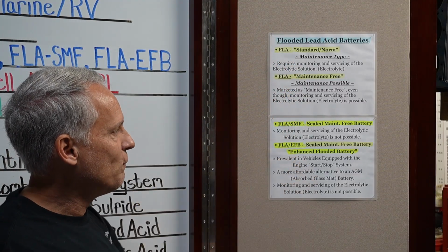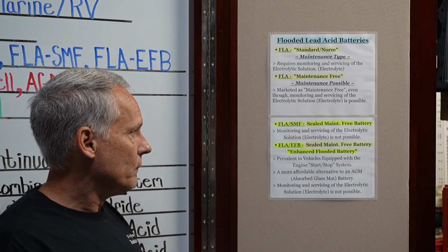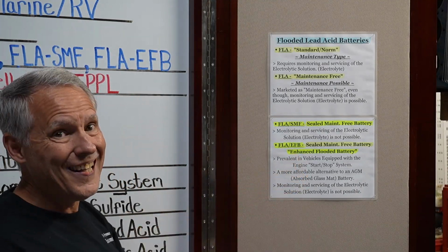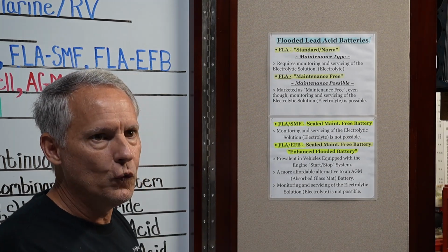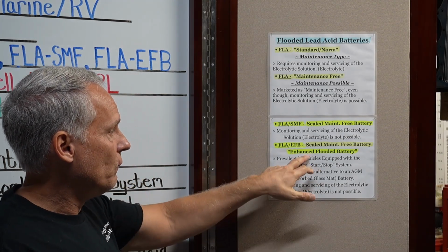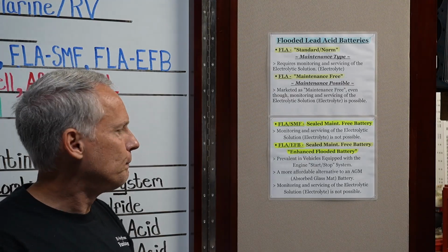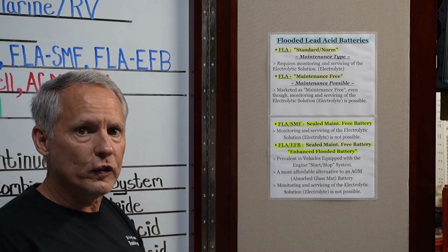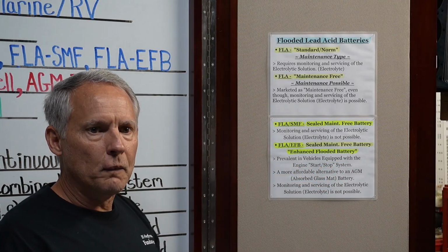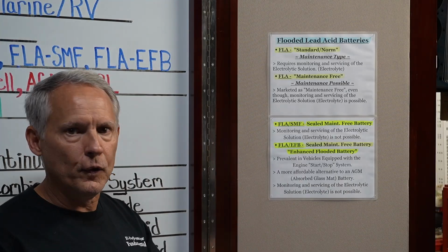But when you get into an EFB, enhanced flooded battery, it is exactly what it sounds like, enhanced. Right? Also sometimes known as an extended flooded battery. Like I said, different manufacturers, I don't know why they do that. But this battery was actually invented by Exide, and it's called an enhanced flooded battery. That's what it is. Okay? It's prevalent in vehicles equipped with the engine start-stop system. The vehicles, when you come to a stop, the engine shuts off, and you go to take off, you hit the gas, the engine starts back up, and away you go.